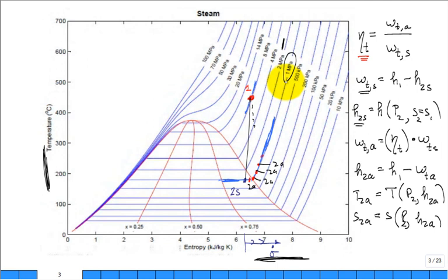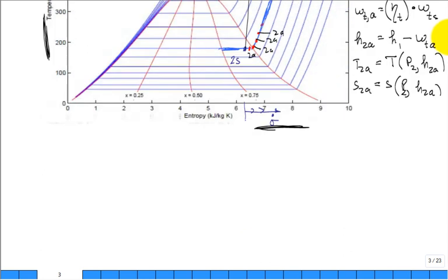All right, now, is that good for the turbine? Let's talk about the pump. So you come down, let's just think about the pump. How about the TS diagram? Should we draw it all in the TS diagram? Only if you have a magnifying glass, then you can zoom in right in there because it's all tucked in there, isn't it? So what you do is you say, for the isentropic efficiency of the pump, it's going to be the ratio of the work.